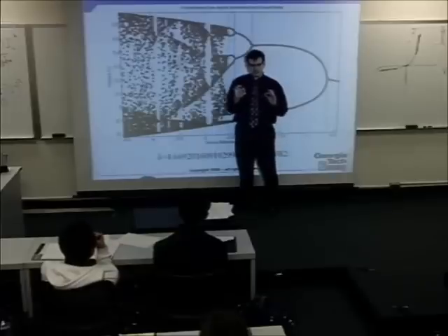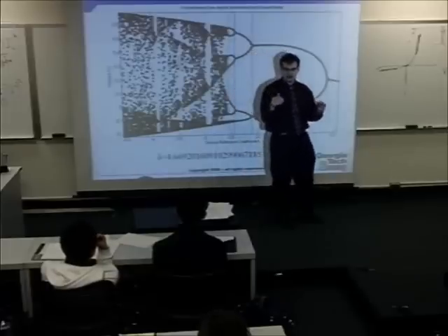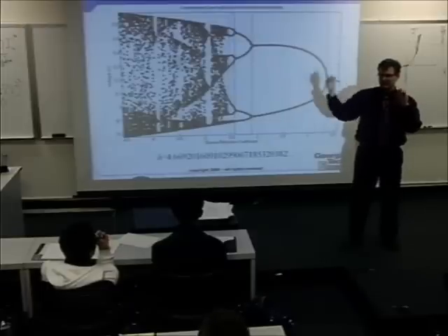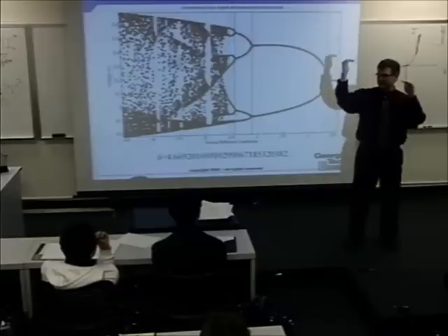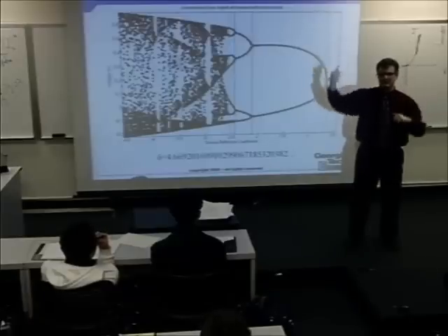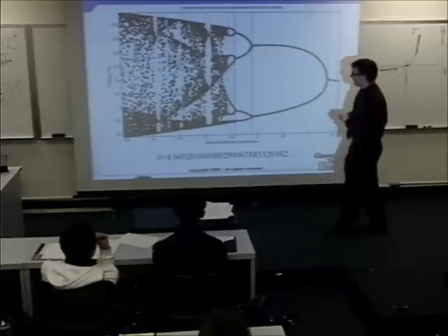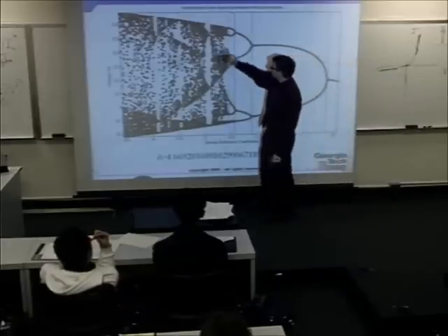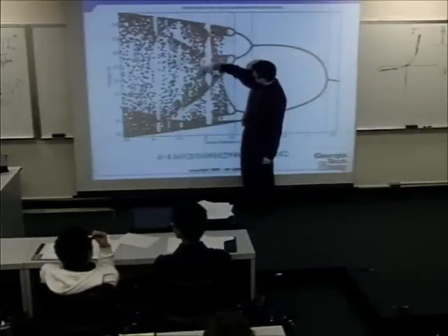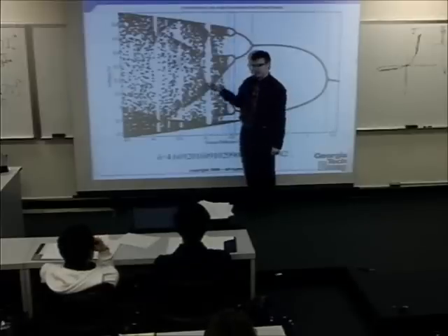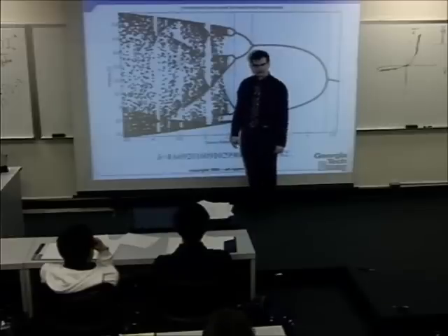I can try to simulate that on like a SPICE program, but it turns out that unless I get infinite precision, it doesn't take long for the real world output and the SPICE program output to diverge and then completely disagree with one another. Very interesting property. The other thing to notice here, too, is that within the chaotic region, you have these islands of stability, where the system slips back into stable modes. And they're usually odd stable modes.